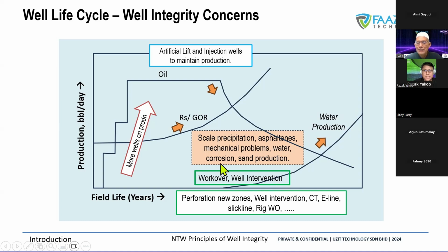This is where well integrity starts to be affected. Okay. When you produce from this well, you are also going to produce at high volume, so the velocity of the crude will be almost erosive. So you might see some wear and tear when you're producing, from the tubing and from the facilities, so you are actually reducing the well integrity as well. But at the same time, when you're producing too high, you have some sand too. Sand is very abrasive, it's going to be a problem. But as you know, when the oil comes up to the lower pressure at surface, you have the gas oil ratio. The gas is going to be coming up from the reservoir inside the crude, and it can be produced at surface.